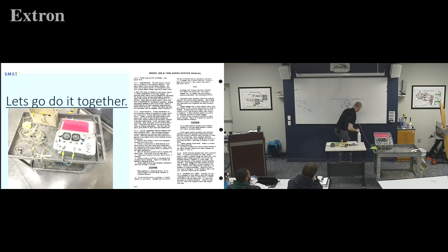The other tube, we would hook up to the pitot tube. Notice I labeled A and B. If you hook them up backwards, we'd be putting the pressure on the wrong one, right? But this says pitot, this says static, so I have them hooked up correctly. I'm going to just put a piece of putty on here for now because I don't really have a pitot tube. So the way this box works,